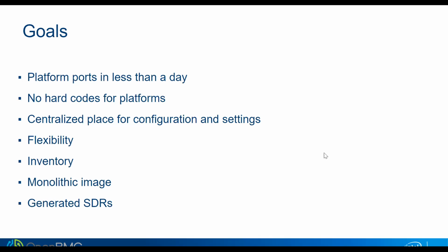If you look at the probe statement itself, which we can do later, it takes a D-Bus interface and a key value pair from that interface. FRU Device just happens to be the biggest usage of that, because EEPROM FRUs are an easy way to determine that something is there. But you could totally write your own application that exposes some sort of D-Bus interface that says this thing exists and use that to install the configuration.